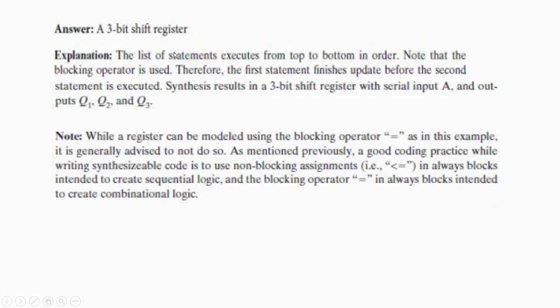So here the statements execute in top to bottom order. It's a general order of execution, but the order doesn't matter in some cases. In this last case we mentioned, the order does matter, but in the case before that, the order did not seem to matter, right? We didn't have an additional input, so the order didn't matter. Now here the blocking operator is used, which means the equal to sign is the blocking operator, as we have learned about operators in other programming languages.